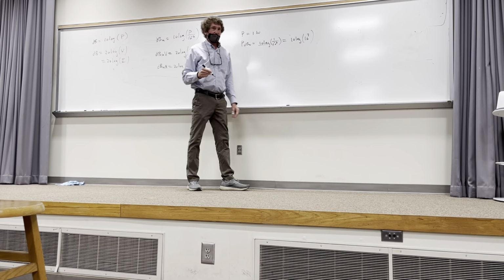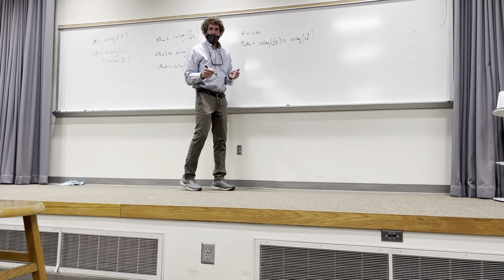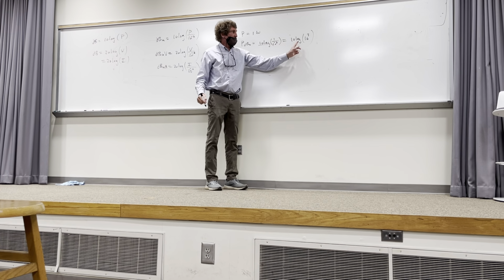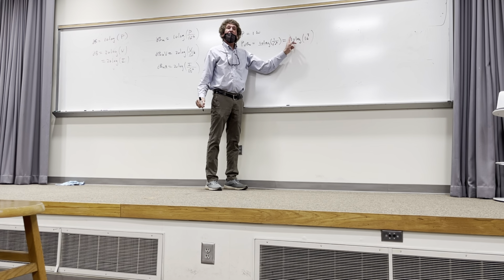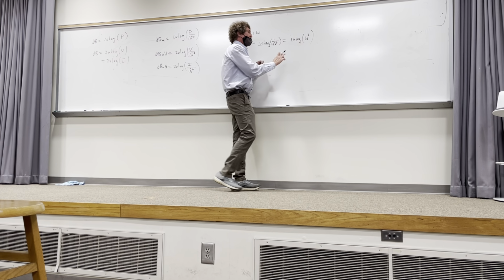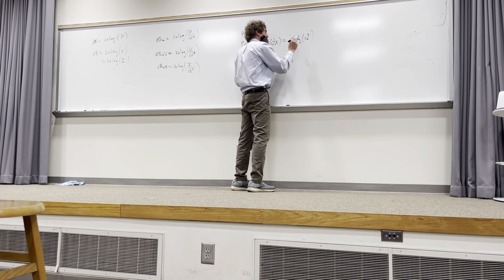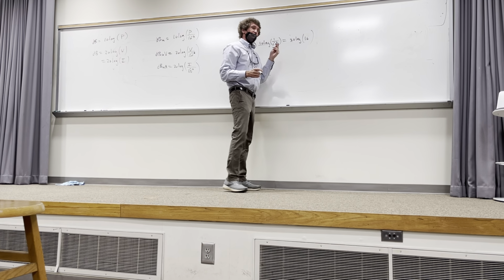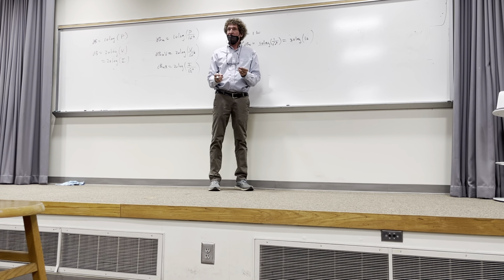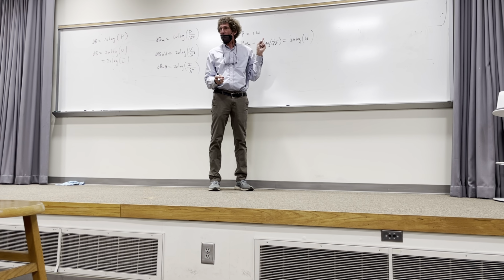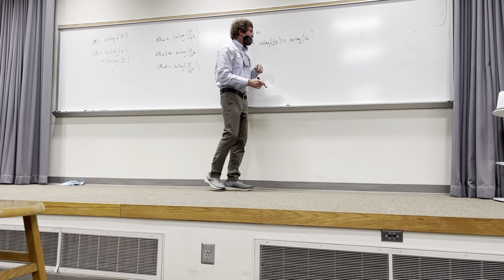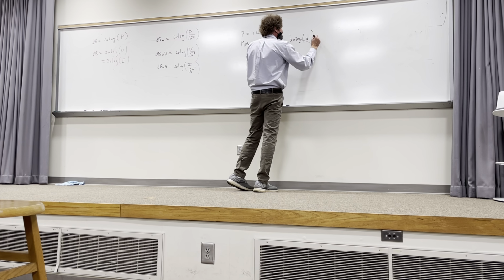Okay, how do you do that just in your head? Well, you all see if you take the log of a to the b, the b can come out front, right? You all with me? So that means 3 can come out front, make that 30, get rid of that. And what is log of 10? 1, right? Log base 10 of 10 is 1. If it's ln, you'll get a different answer. But you all follow me? And so therefore, since that's 1, it's just 30 dBm.